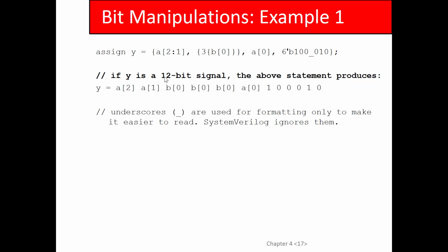Now you can also put underscores in constants, which is kind of convenient when you're trying to split a binary value up into fields, as you would for, say, floating point or instructions and that kind of stuff. So you could say 10'b01_000_11111.